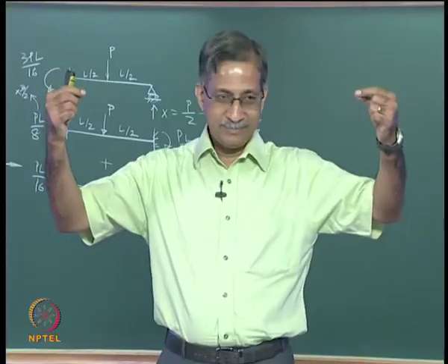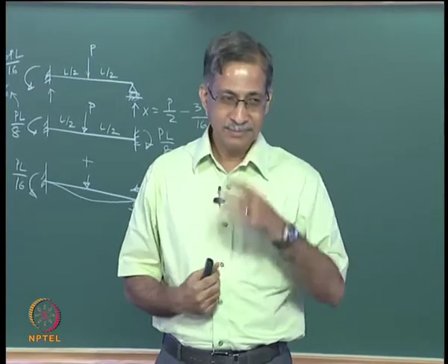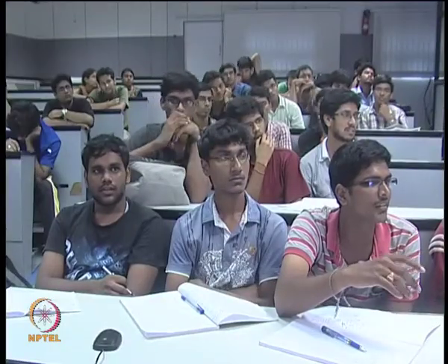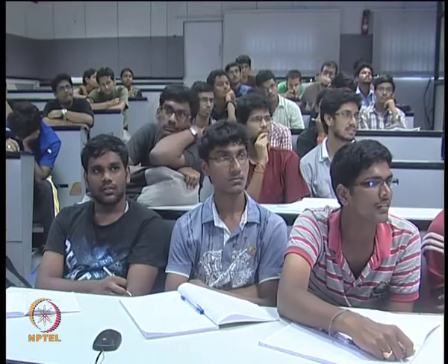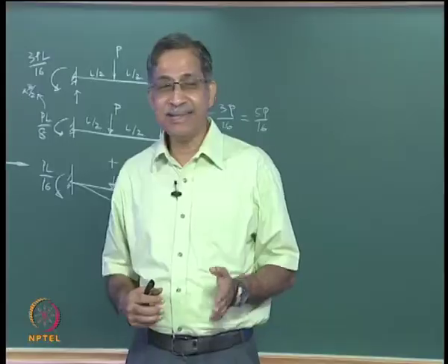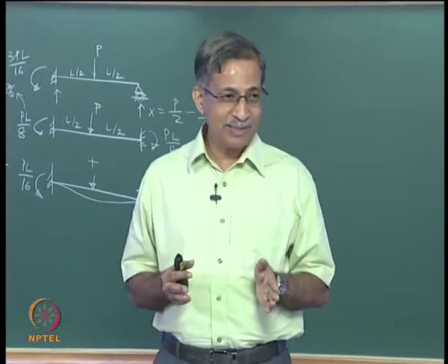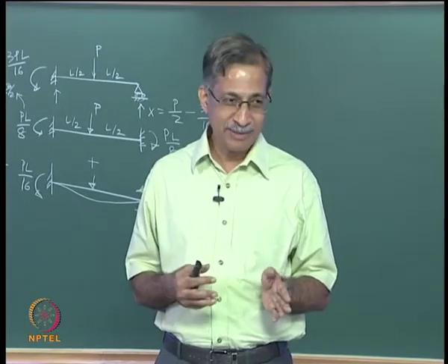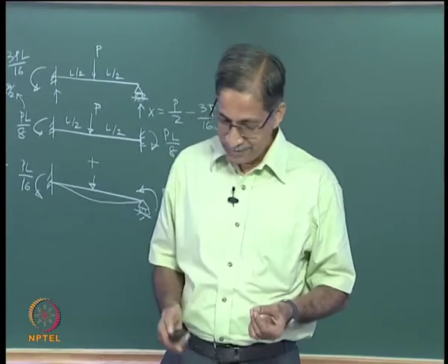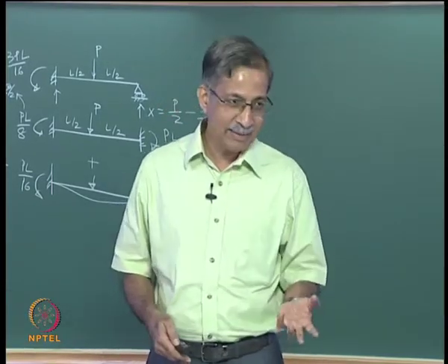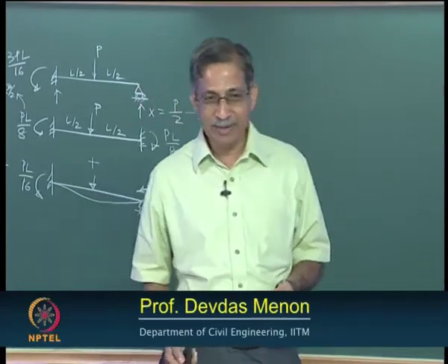GH is loaded. What's your hunch? What's your intuition? CD and EF are supporting, because they are stiffer. See, the stiffer fellows will support the not so stiff beam. Can't you feel it? Ultimately the deflections are the same. So it does not matter. Let us say you made a mistake, it will show up with a negative sign in your reaction, but it is good to get it intuitively right straight.